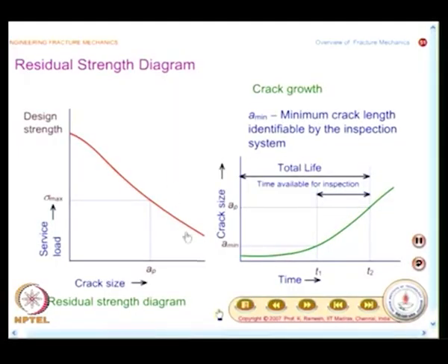In fact, if you look at conventional design also, when you look at railway stations, when the train stops, there would be someone sitting below and hitting the bottom of the bogies at appropriate places. He is actually doing a vibration test to find out whether there is any structural damage. And for aircraft, every time they land, they do certain minimal inspection, and aircraft go through exhaustive structural monitoring during their service life. So, you need to know how often you should inspect and what you should look for in each of those inspections. You may have a preliminary inspection, you may have an exhaustive inspection in between. How do you go about collecting the information to decide on these issues? That you get from a graph like this.